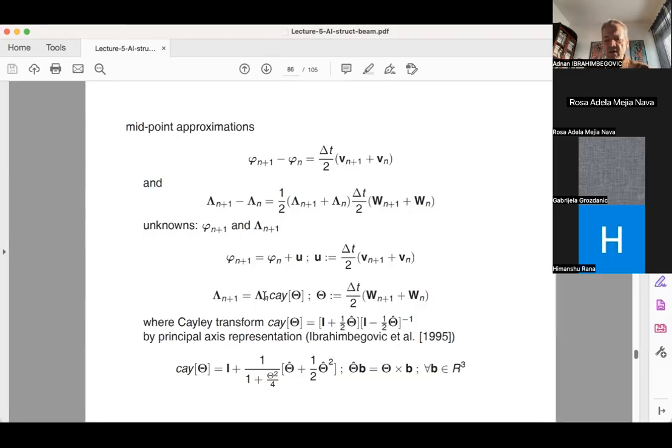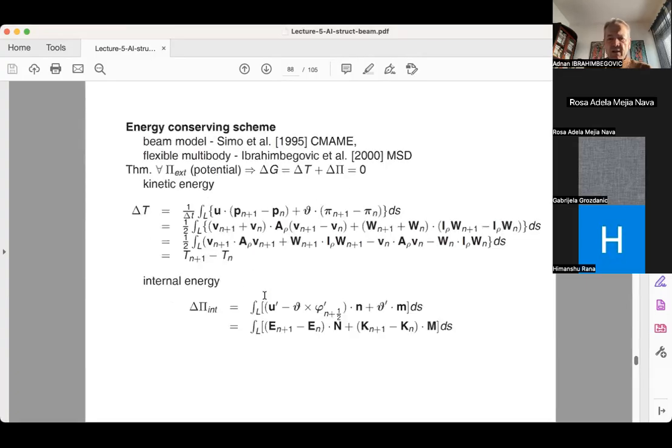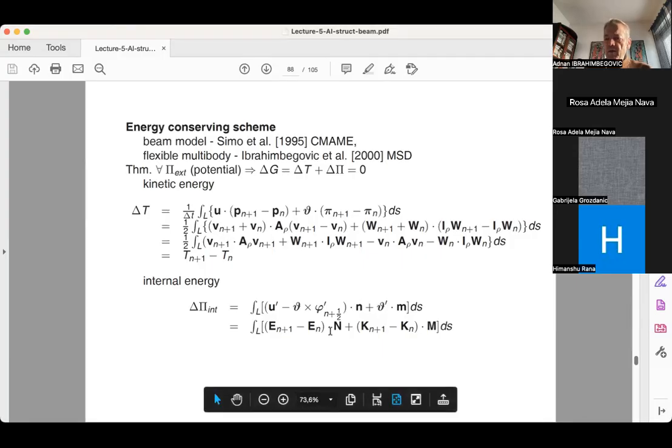That's the only complexity. There's really no point of going into this detail because there's just lots of details, but it comes down to things that we already discussed and just more laborious. And then the trick is, if you now want to make a energy conserving, and you're running this with the midpoint scheme, where this is computed, the variation at n plus 1/2, you have to leave this, the constitutive, the stress resultant N and M, or in the material representation, uppercase N and uppercase M, without any index, because you're going to be using something called algorithmic constitutive equation.